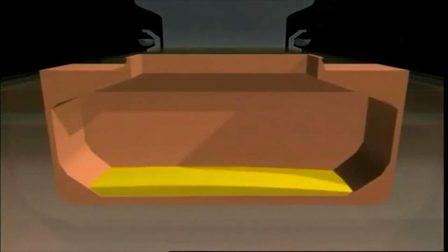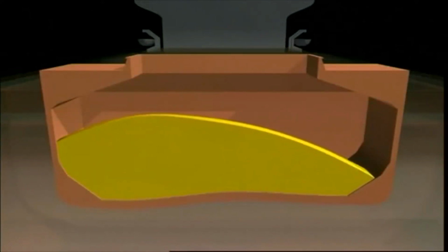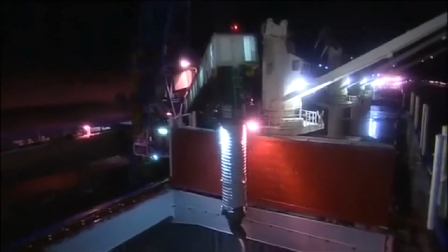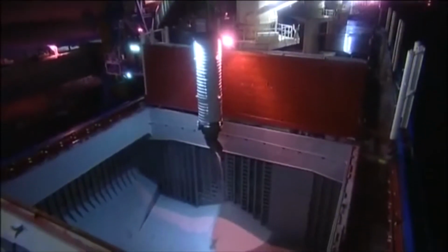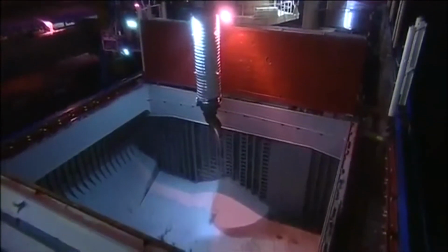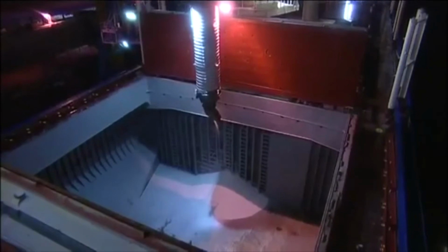Likewise, if cargo is unevenly distributed away from the vessel's center line, this will induce twisting and the subsequent warping of the hull structure, as well as placing stress on the transverse bulkheads. Therefore, the agreed loading sequence should be followed precisely, and cargo must always be stowed and trimmed appropriately within permissible limits.